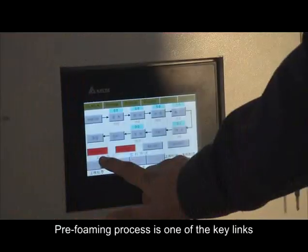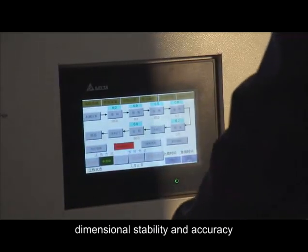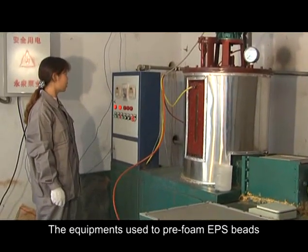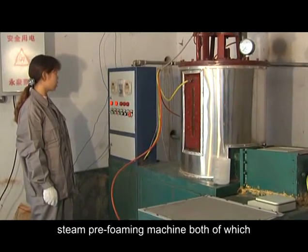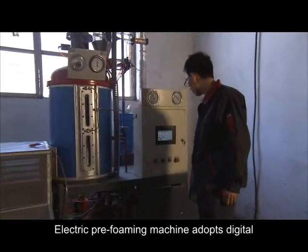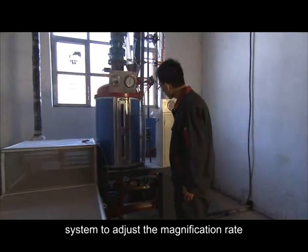Preforming process is one of the key links which determine the model's density, dimensional stability, and accuracy. The equipment used to preform EPS beads mainly include 2 kinds: electric preforming machine and a steam preforming machine, both of which use the most advanced PLC technology. Electric preforming machine adopts digital system to adjust the magnification rate.